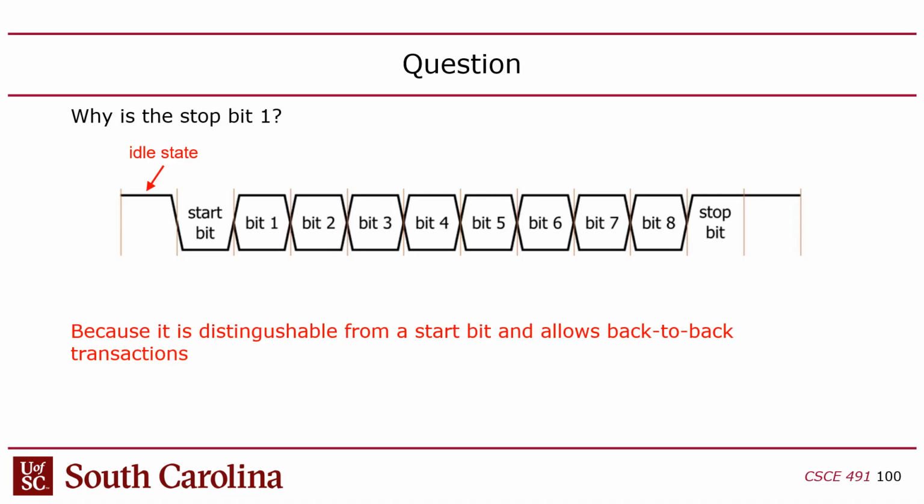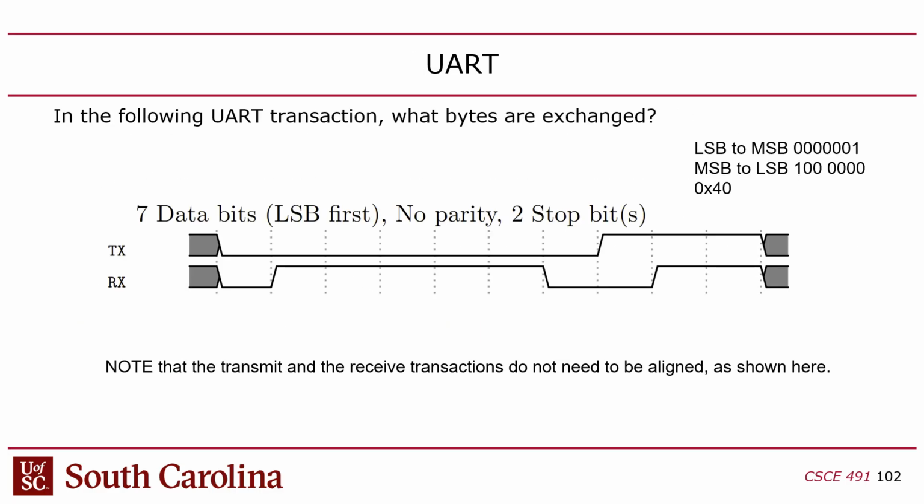Now, if you're doing UART over USB, I don't know if it's using exactly the same protocol. It's taking the UART and encapsulating it inside of USB packets, right? This timing diagram is assuming you just have straight UART, not UART over USB. USB is a packet-based protocol, where you would be bundling these messages over packets. In that case, you're kind of emulating UART. You're not directly implementing UART signal-wise. All right.